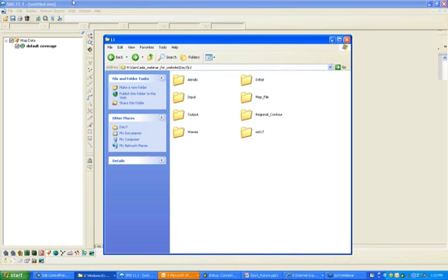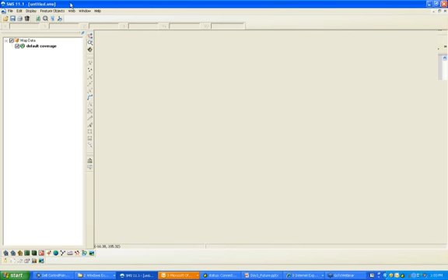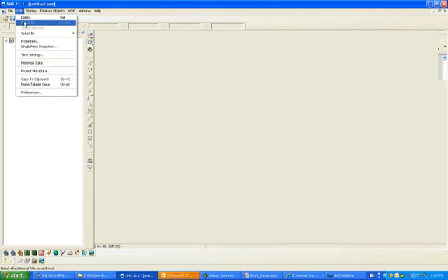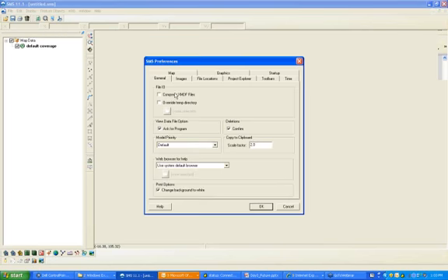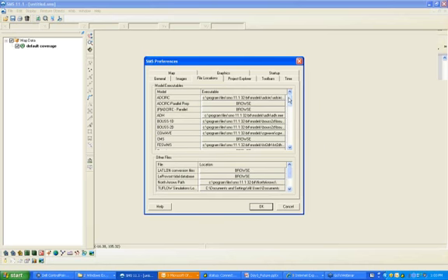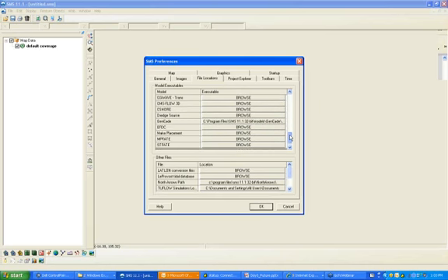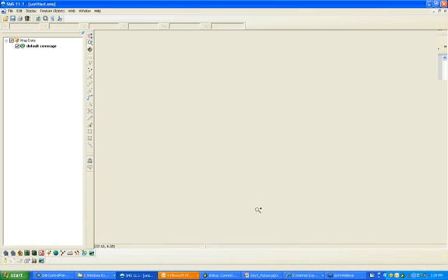So again, when you start up SMS 11.1, you already have it open. Just as a reminder, the first time you use SMS, you need to go Edit, down to Projections, and then define where the location is of your executable. You do that by going into File Locations, and then scrolling all the way down to Gencade, and then defining the location of your executable. I'm going to click OK. And now we're just going to start this case from scratch.